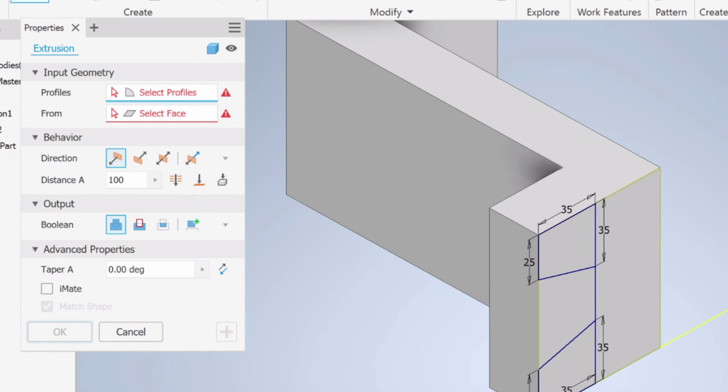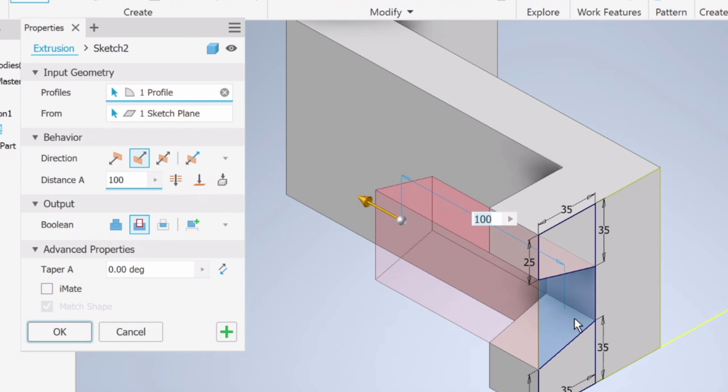So in order to remove, you can check with this boolean operation in the extrude command box. Here this is for join. Usually we choose this one to generate solid, but in case you need to cut, you can choose this option, cut. So when you choose cut and come over here and pick that, see what happened. It removed the material rather than generating it from the profile that you selected.